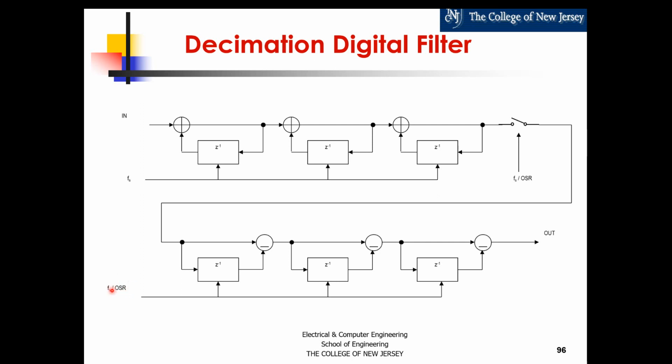This is an integer greater than 1. So we say that this approach of sigma delta analog to digital conversion is an oversample system, because we are oversampling. This frequency is higher than this one, and this is the one at which your output is coming through, so this is a useful rate at which you can use the conversion.